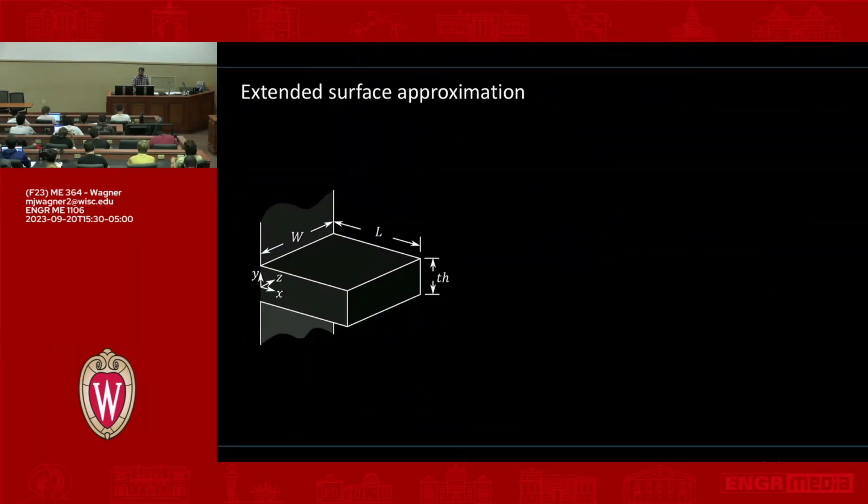So there is a computation that you can do to justify this 1D assumption. And it is called the Biot number. So B-I-O-T, not B-O, just B-I-O-T. Biot number, again, a French person. And the idea is that you're trying to relate two quantities to each other, right? It's a ratio of two quantities.